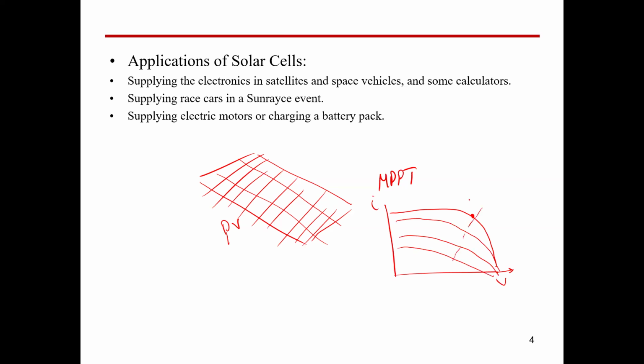So this is called the MPPT algorithm, which is going to make control for your PV panel to achieve the maximum possible power, whatever the incident light or the light intensity we have during the daylight time. So this is one interesting topic of the solar cells. We use it in our life today.